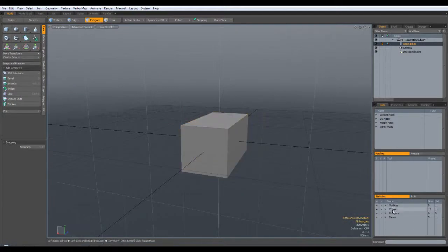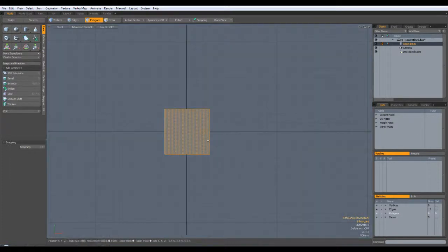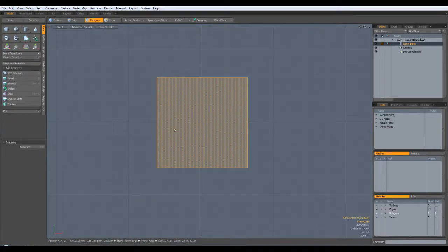or you can come down to the statistics pane down here. Now if you want to select polys, we'll be using these, or I'll be going into a bit more detail about these, but if you pull down this little drop down there, you can select polygons by material, part, vertex, type, etc. And we will be doing that at later dates. Or you can just hit the little cross there to select everything within that group of polygons, or minus just to unselect. So we're going to just select those like that. We're going to jump over to a side or front view, it doesn't really matter.